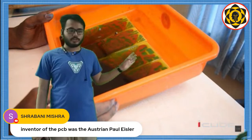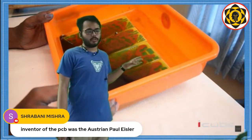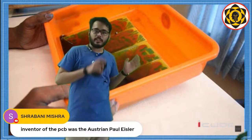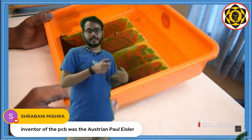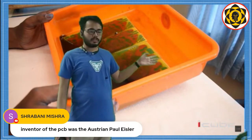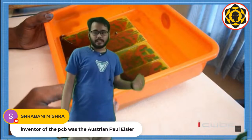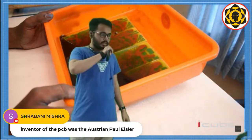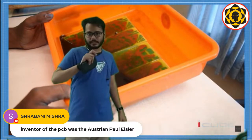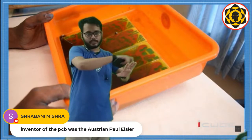So this is the solution. As you can see, as you start washing, the copper part will wash off. What is basically happening is we are introducing copper to the acid, so the copper is getting dissolved by the acid. Since the paint is on the copper over this part, it's preventing the copper from getting dissolved. It's like you first rub the whole page with a pencil, then you put your hand and use an eraser to erase the other places.